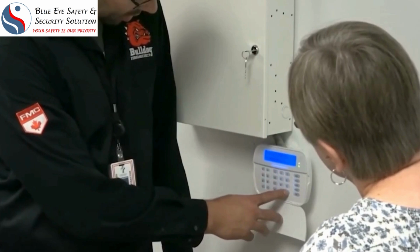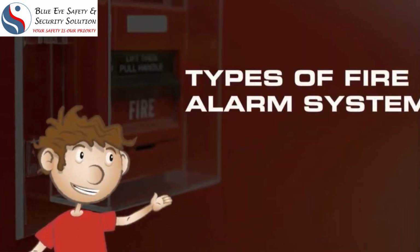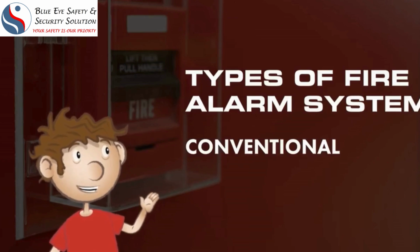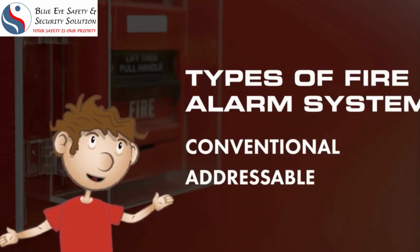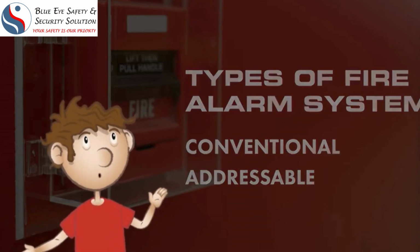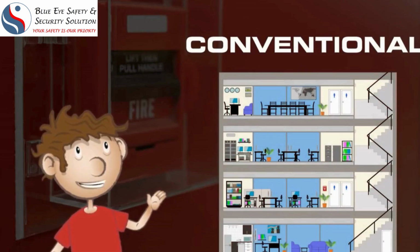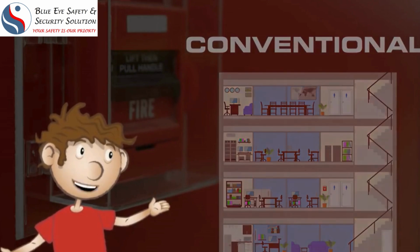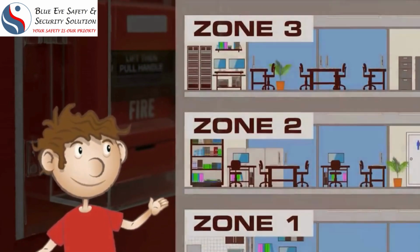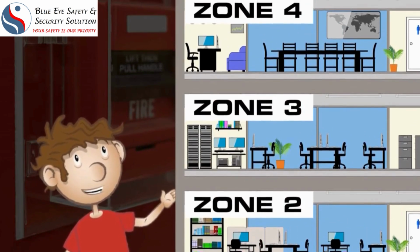Now, let's take a look at the different types of fire alarm systems. There are two primary types of fire alarm systems, conventional and addressable. While both interact with devices and other components in a similar fashion, they differ in how they're connected. A conventional fire alarm system connects the control panel with each device on a separate wire and is typically set up in zones. This way, when a device is activated, the system can identify the zone and help narrow down the location of a potential fire.